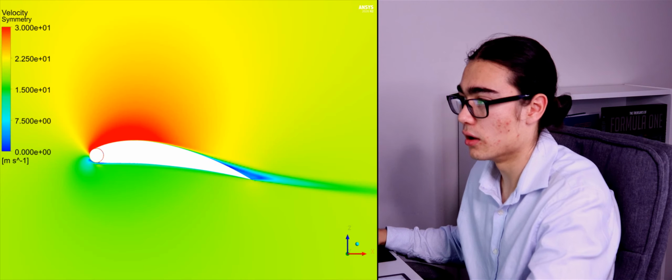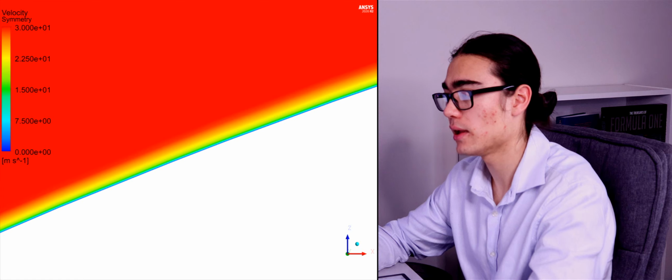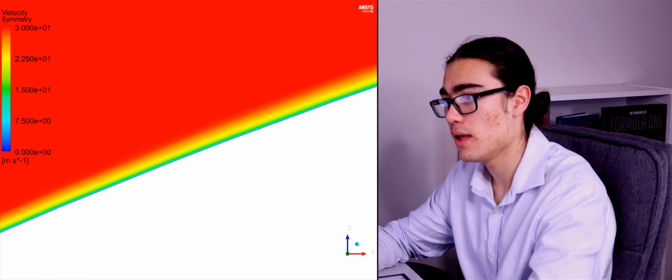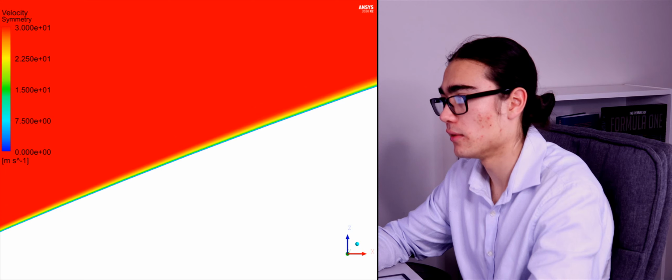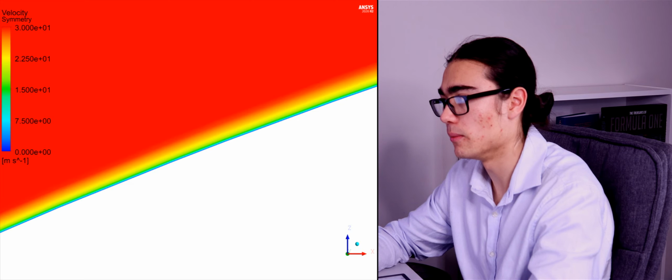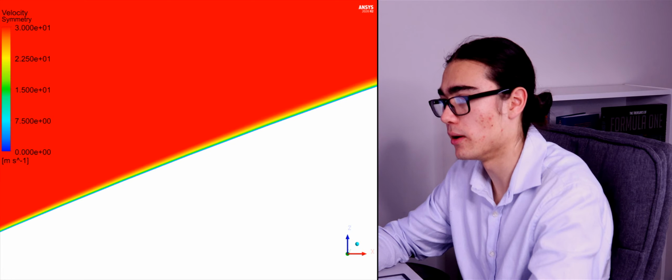So I've actually got a close-up here of the boundary layer just after the cylinder. This is the regular wing and there's the Magnus wing. You can see there quite a sizable decrease in boundary layer thickness, even though we're just behind the cylinder.